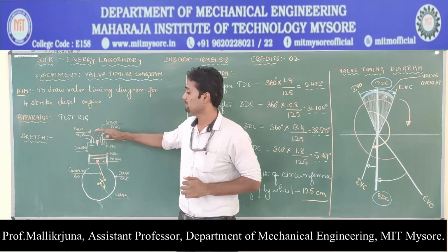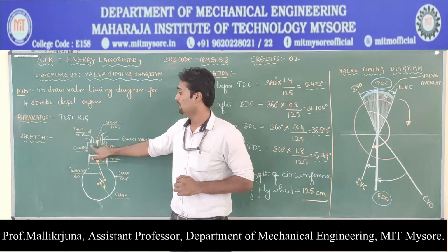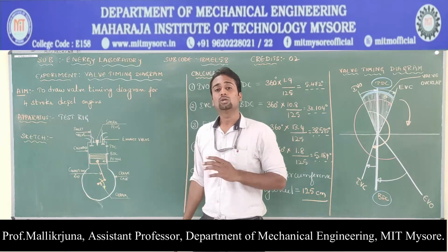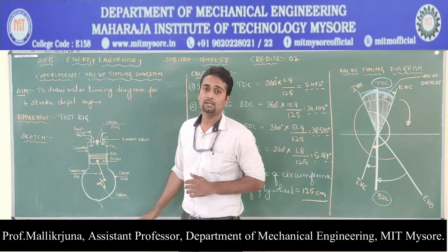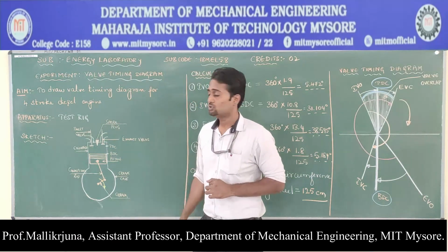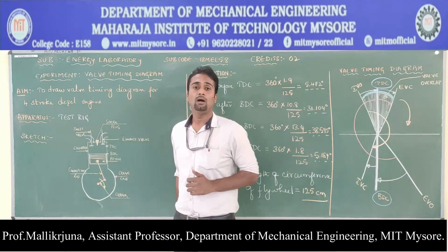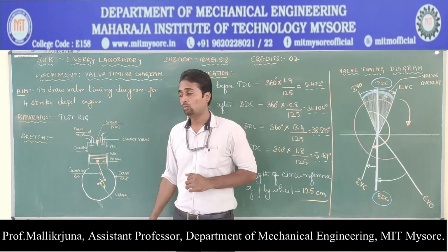The last stroke is the exhaust stroke, during which the exhaust valve has to open and inlet valve will be in a closed position. So the BDC to TDC momentum of the piston forces all the exhaust gases into the atmosphere. So this is how the operation occurs in a 4-stroke petrol engine.